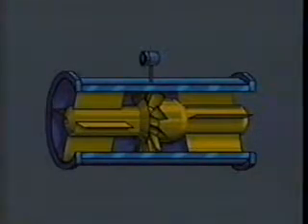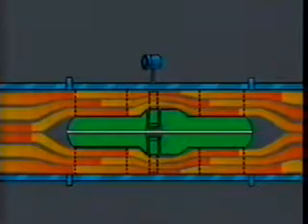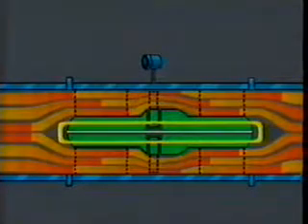The turbine rotor blades are set at a predetermined angle. This angle relates the flowing stream, angular velocity of the rotor, and the frequency of the meter. The rotor rotates on the center line shaft by means of a bearing. This bearing is either lubricated by the meter fluid itself or permanently sealed. However, to minimize the load on the bearing, the rotor also floats.